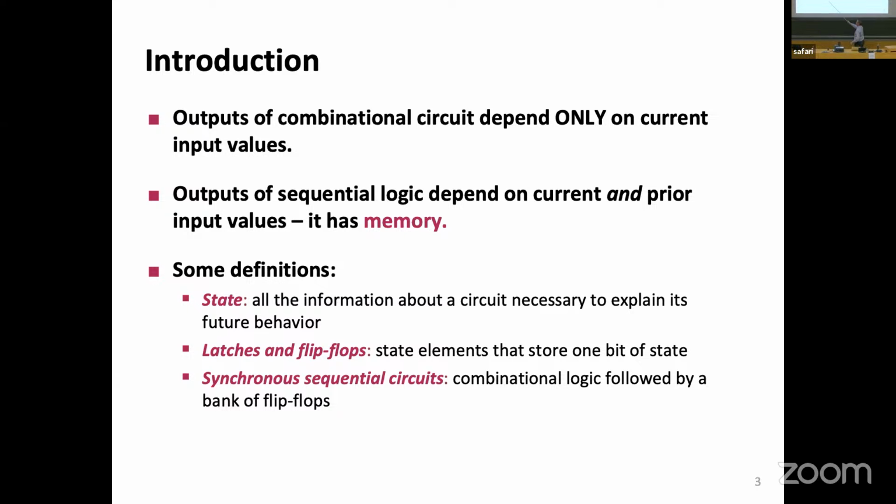We will hear about latches and flip-flops. These are individual elements, one-bit elements that can store part of the state. So we will combine multiple of these to store the state in a circuit. And we will call circuits that are made out of combinational logic, which we already know, and the state elements, synchronous sequential circuits.